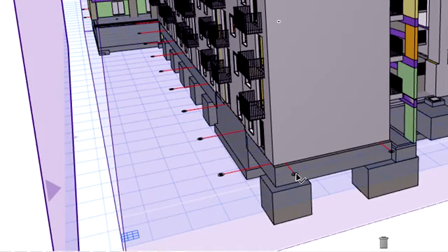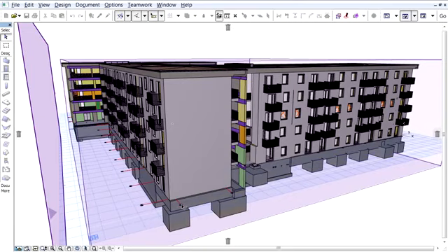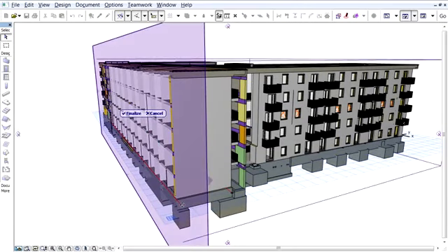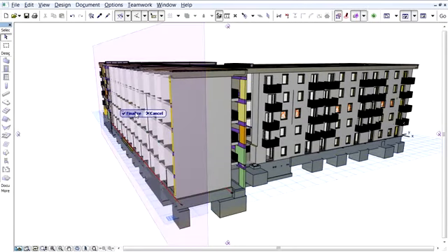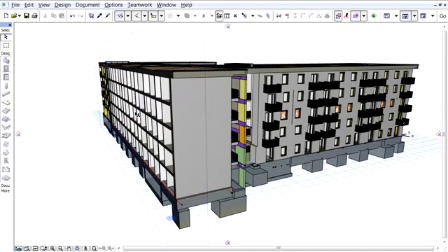Meanwhile, we can use the mouse and find the most appropriate element edge or node with the help of the Smart Cursor in 3D. Finally, we can release first the mouse button, and then release the Shift key to finalize the cut plane at the given location.